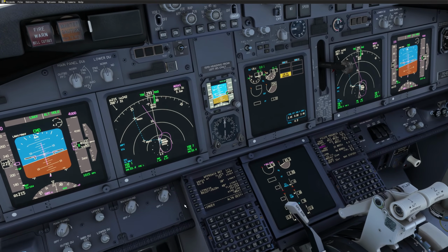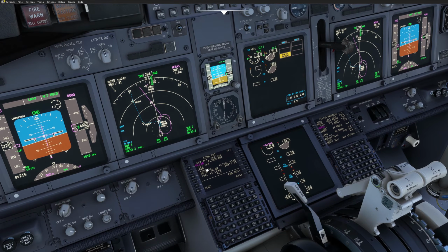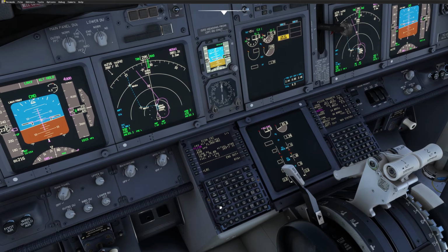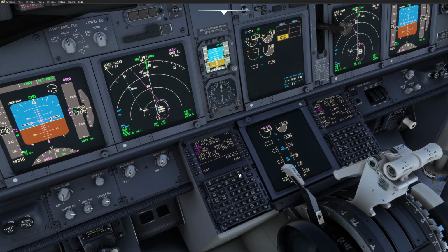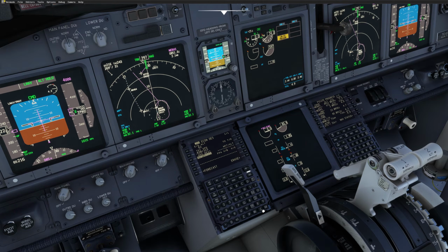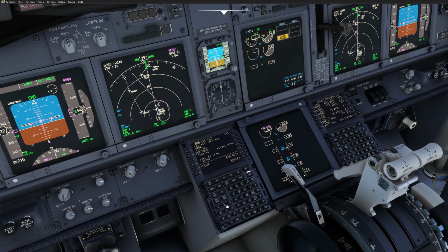What I will do now is cruise page. You see we have flaps level 130. So we are going to set 4,000 feet, the actual altitude. And we are going to set the descent speed. We'll keep it around 220 knots. 220. And if you go to cruise page, you can put as well 220 later on.